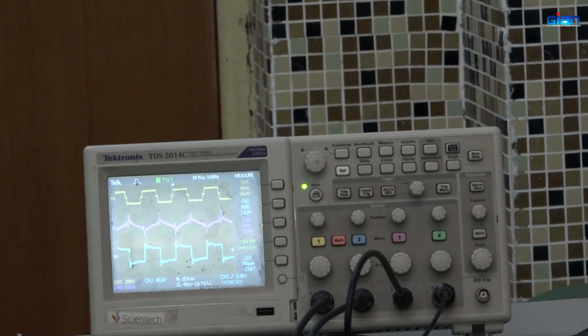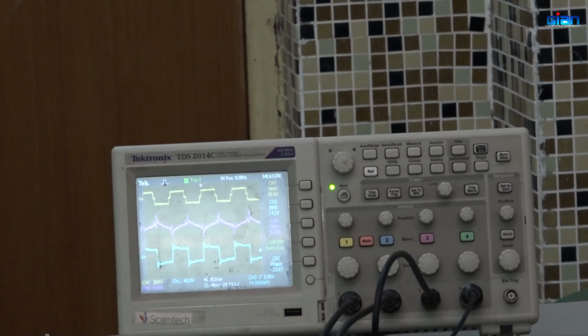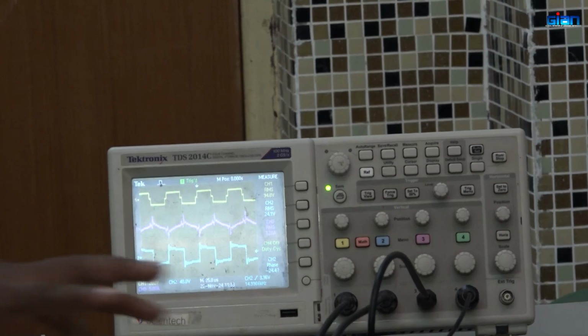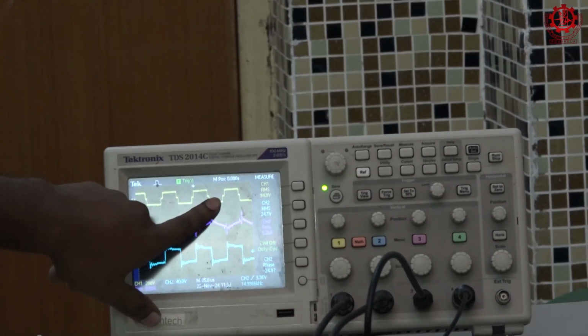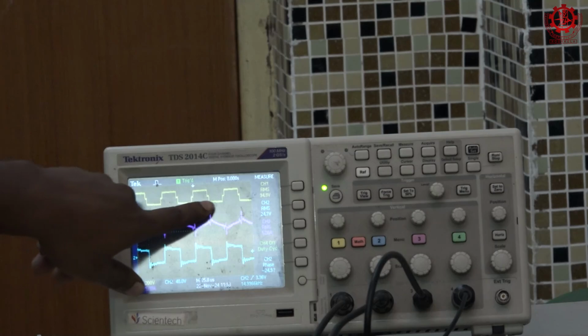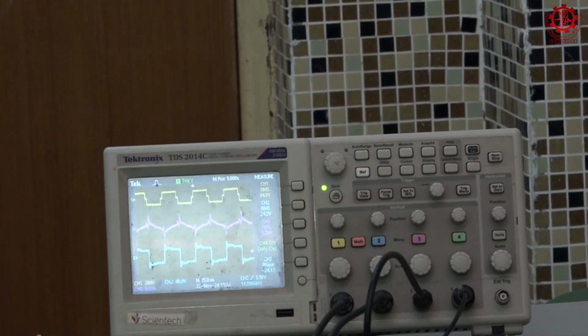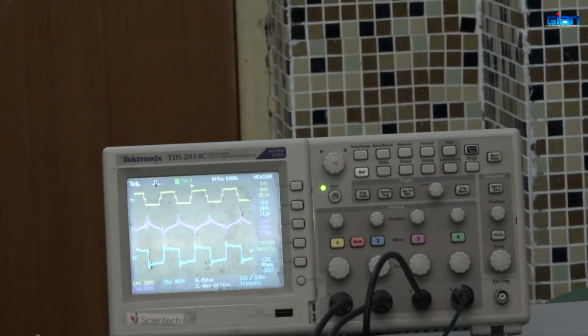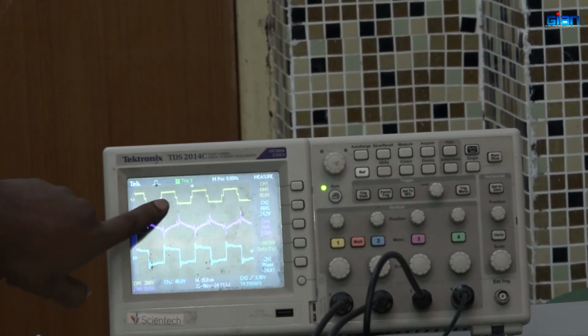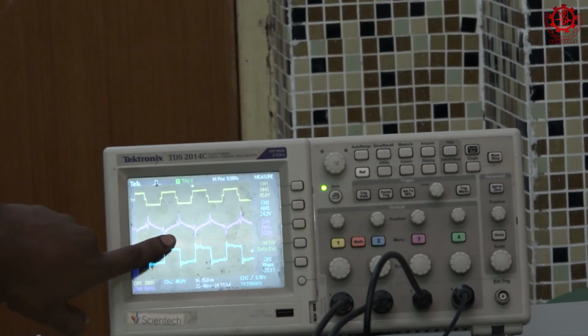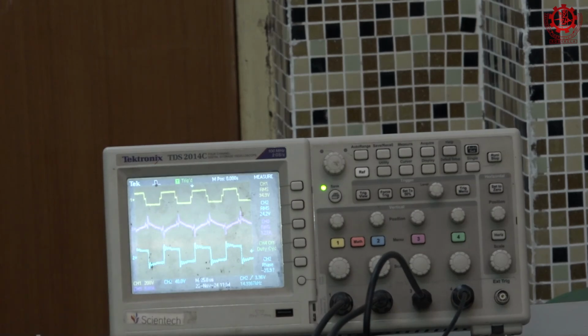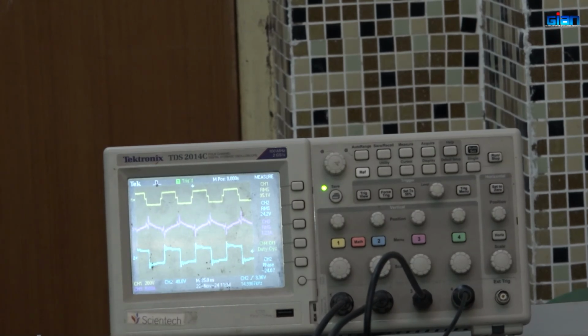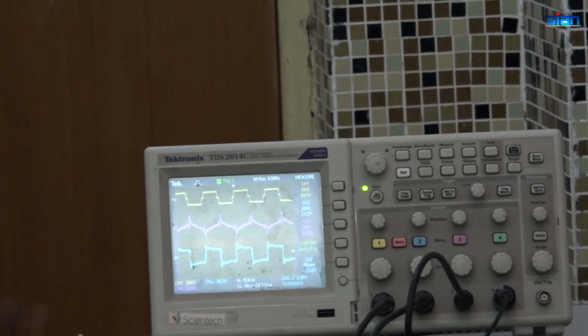If that back power flow is increased, what will happen? The stress on the switches will be increased. So to increase the efficiency, if we give the phase shift between the legs, it will make a short there and bypass that back power flow through the diodes. It will freewheel it. Like that we can improve the efficiency. So we can see that there is a quasi square wave here, so EPS is also working. This is the inductor voltage in the secondary voltage waveform. So this is about SPS and EPS.